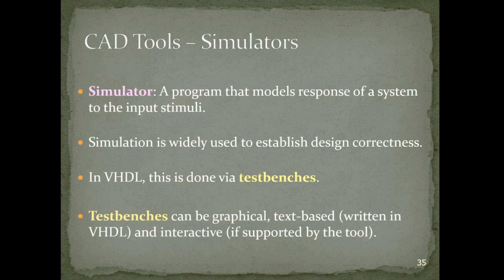In Xilinx in particular, those test benches can be graphical test benches. And this is why we are using, again, version 10 rather than a newer version, because newer ones no longer have the graphical ones, and those are invaluable for our purpose. We can also use text-based test benches, which are essentially specific test benches written in VHDL, but those are a lot more complex to create.